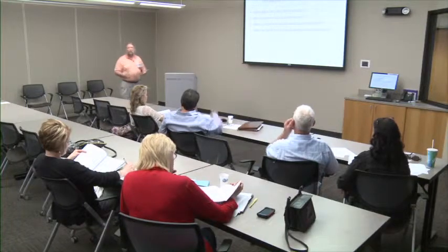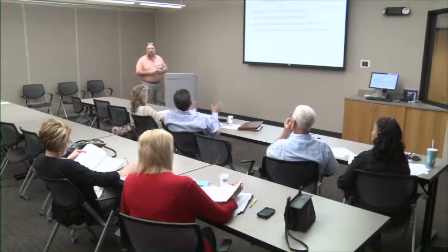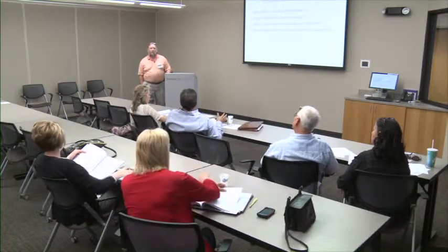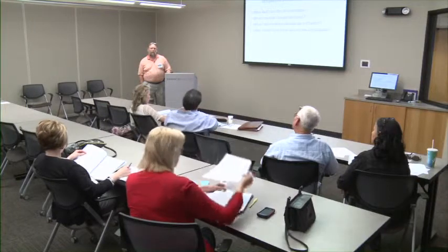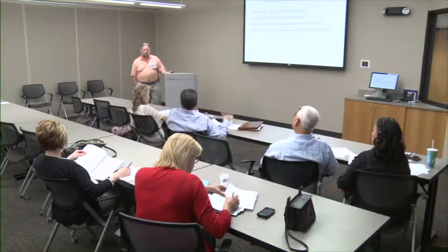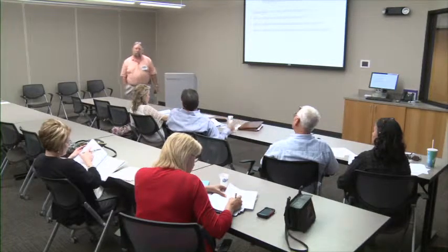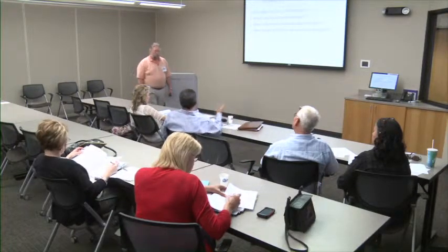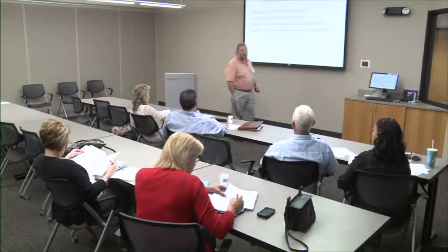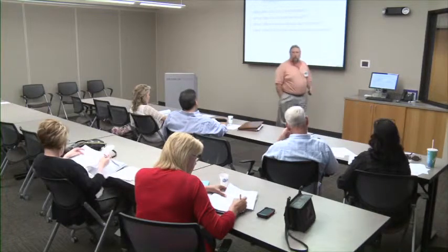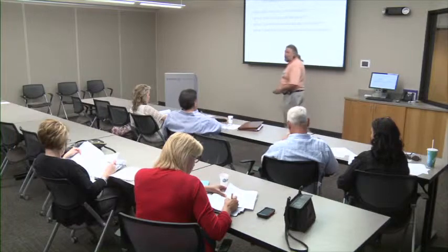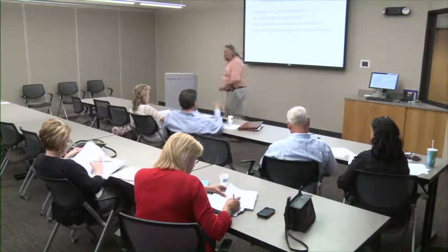Simple concepts. Yes? Usually as an owner, I probably ask also the software to do the analysis for the as-built and compare with the baseline so I can see if he's delaying or any potential claims on the contractor side. So I have to have everything from the contractor as an owner. As an owner, we probably want everything from the contractor if they're willing to give it. But if we do that, we definitely have to put that in our contract documents that you have to provide us with all that information. Yeah, because they give you a monthly update, they play tricks on you, and if you don't see it.